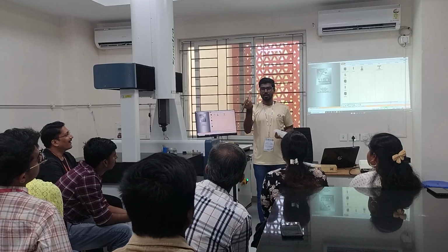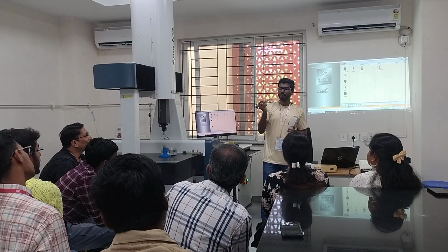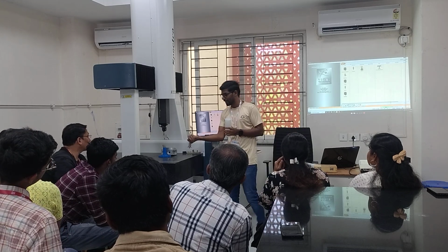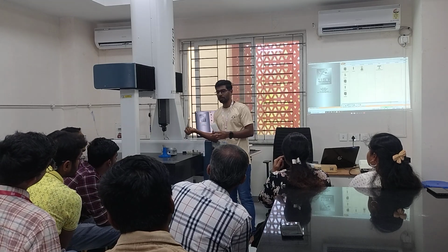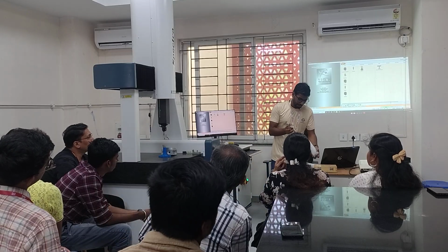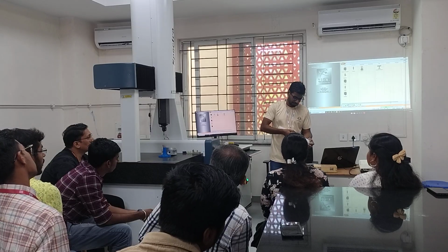This is given by the company and it has a 29.9983 diameter. So we have to calibrate it and tell the machine, okay, I am calibrating and this is what your measurement should be. That is what is required when you are doing any kind of measurement. Calibration is required not often; every 1 year they prefer to do the calibration.